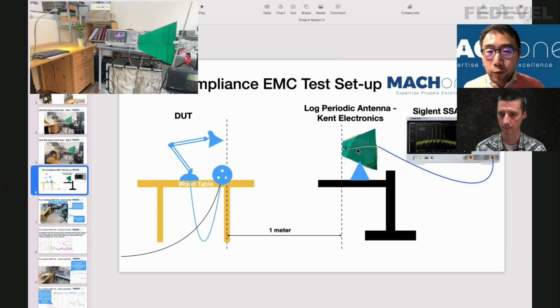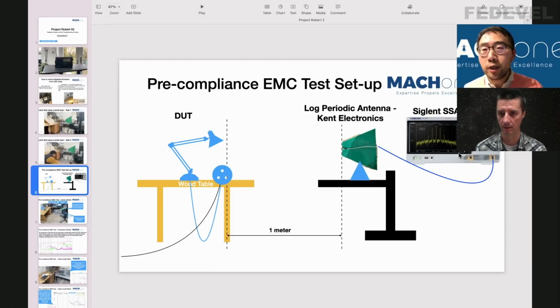In the setup we have a little antenna. This antenna is pointing towards the lamp. Is it important how you put the antenna, horizontally or vertically? Yes, it is important. Normally, you would put it horizontal and then vertical. But because we are trying to fix something, if we measure it in a vertical direction, as we show here, as long as we can always fix it using the vertical, then it's adequate. Maybe initially you try both directions and see which one is noisier, and that's the one you use? Yes, that's a very good method.